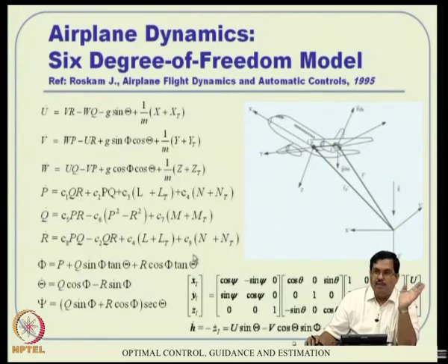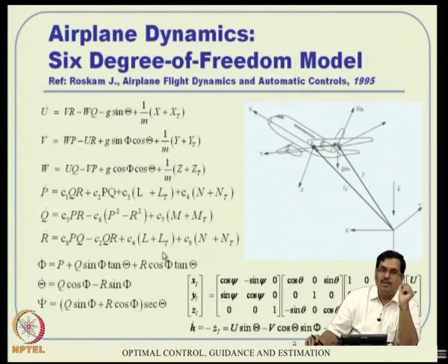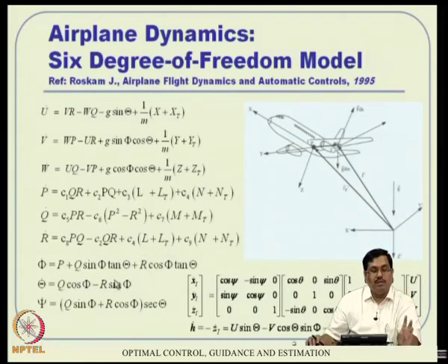Now the whole idea of this MRP and all that, modified Rodrigues parameters, they have already taken into account something called 360 degrees or multiples of 360 degrees. Then only you will have singularity. So one full round you can take, and then still avoid singularity and all that, and you can still talk about a 3-parameter representation, which is nice. Okay, 3 to 3 is actually like, this redundant variable does not come into picture actually.